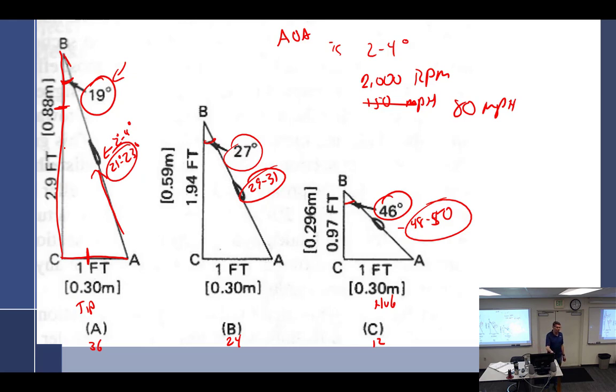So when you go full RPM and you take your feet off the brakes and you're staring down the runway, you're going way past redline. Also, it's not an efficient prop for that engine. It wasn't set up for that engine. But you are going to exceed that little sweet spot, because you're going to redline nearly as you're going down the runway, so you'll lose some efficiency. You said if the propeller's going too fast, it doesn't have enough pitch. If it's going too slow, the engine just doesn't have enough power.